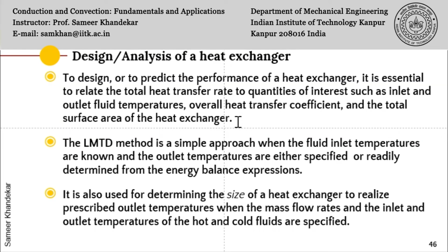So for such type of problems, as we said, the LMTD method is a simple approach when the fluid inlet temperatures are known and the outlet temperatures are either specified by the client or readily determined from energy balance expressions. So when these temperatures are known, the inlet temperatures and the expected outlet temperature, if this is specified, then we will use, as I said, the LMTD method or the logarithmic mean temperature difference method for this class of problems, the sizing problem.